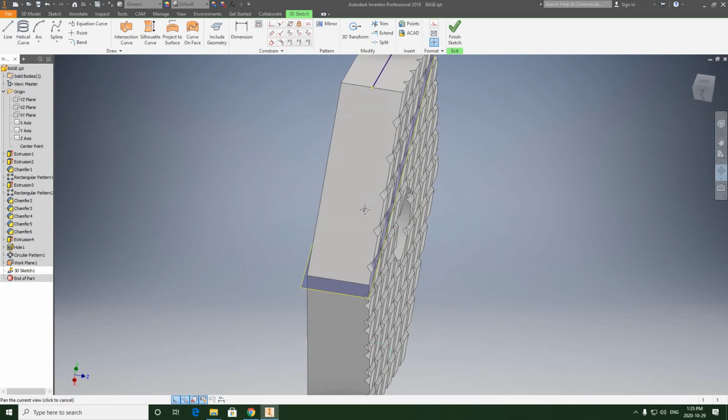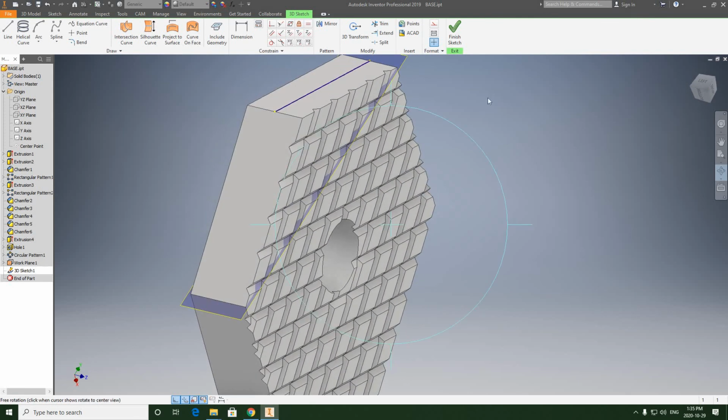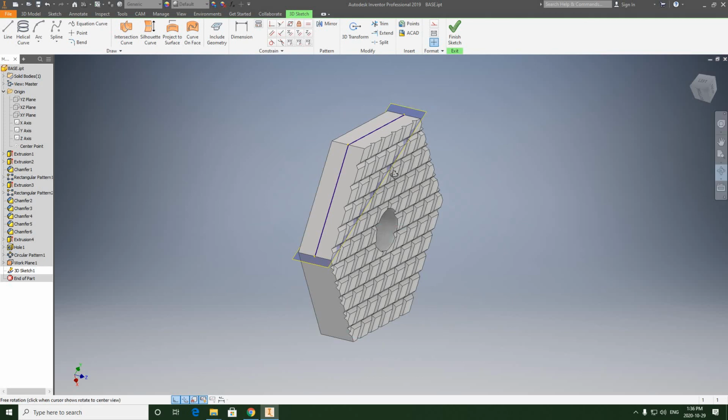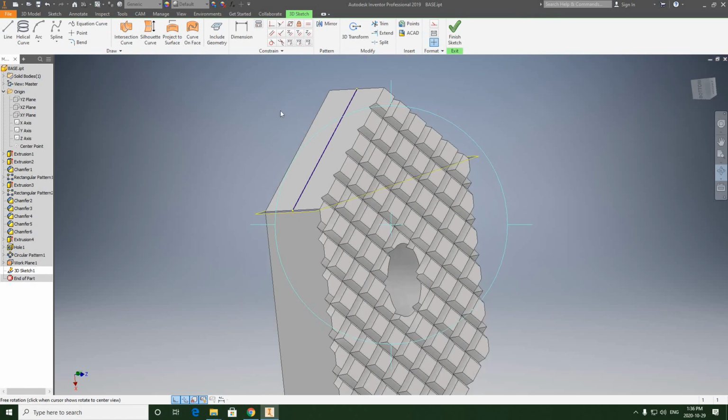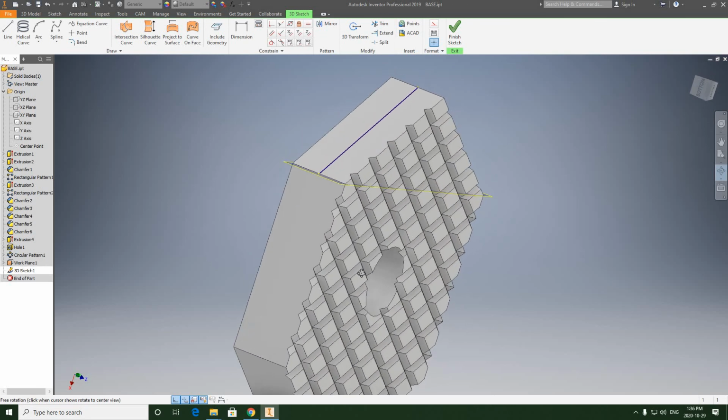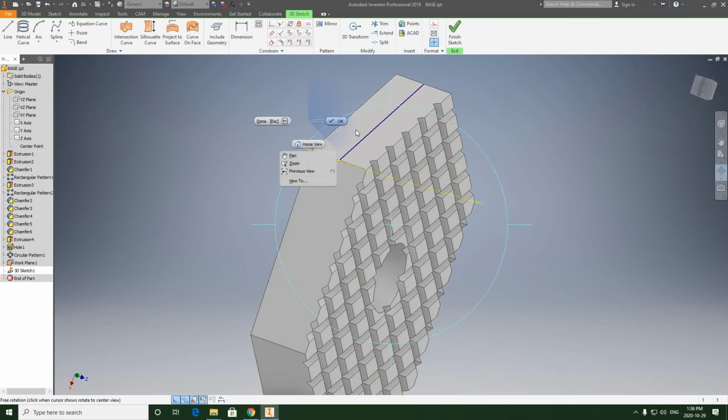Let's free orbit this up. Do this again, line, pick up X, Y, Z, 0 again, come down and find 2.313. If you try to do it continuously, by not ending the line command, you run the risk of snapping things incorrectly, and what you can have is lines in 3D going through the inside of your base, which can be kind of problematic to find and clean up and could affect the sweep operation coming up. So I really recommend that you do it like I'm doing it.